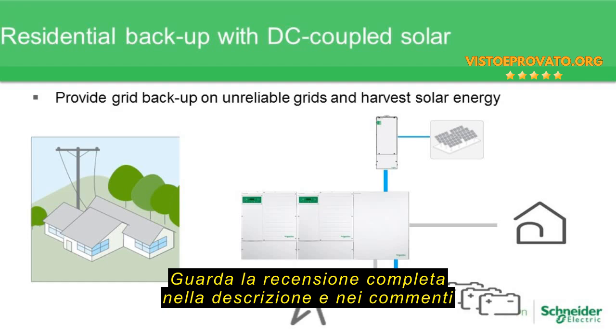From that power distribution panel, we can land our conductors for the grid, for the batteries, and for the backup power to the home. For that home symbol, there would be another little box there that is your critical load panel. In some places, let's say in Australia, they only have a 50 amp panel. And so it's very reasonable to think that putting the entire home onto the output of the inverter could be done. But again, there are some risks that come with doing something like that, because there are potentially some very large loads that could be on there that the customer may not be aware of during a power outage.